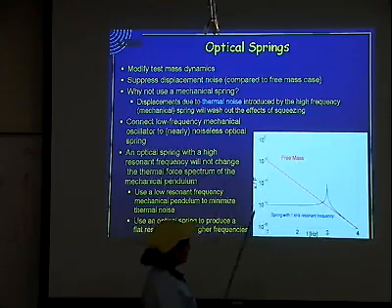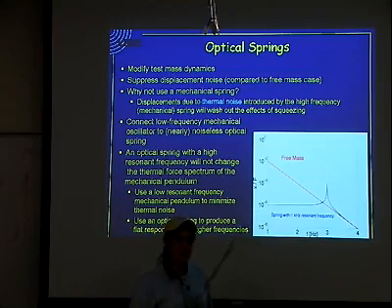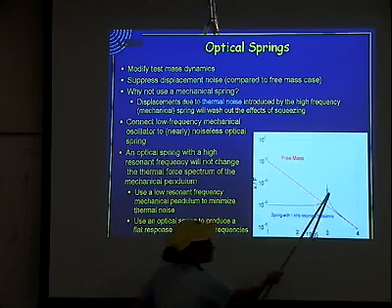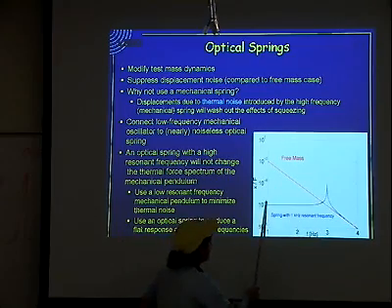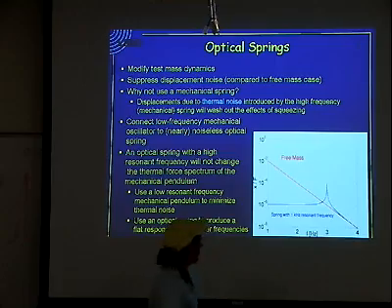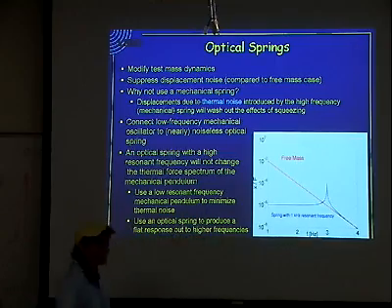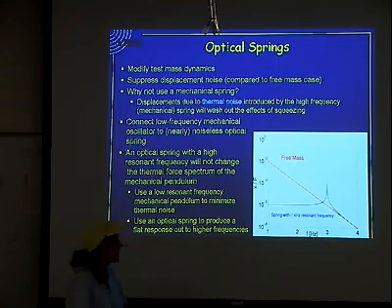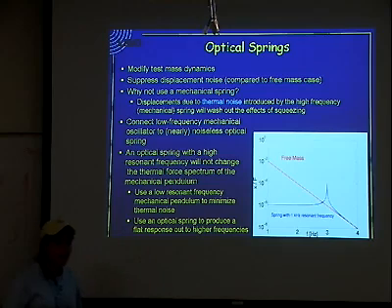And now what happens when you couple this to a much more rigid spring? What happens, of course, is that you move the resonant frequency out to some higher frequency, and in this region here you have the flat response. Now, why couldn't I just do this with a mechanical spring? Why can't I just tie my mirror to a nice old clunk spring? And the answer is the thermal noise from the mechanical spring would dominate the whole motion.